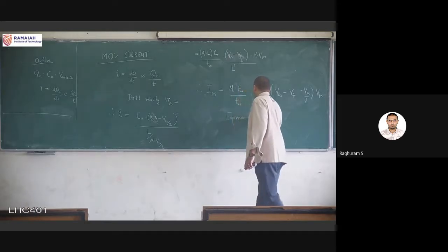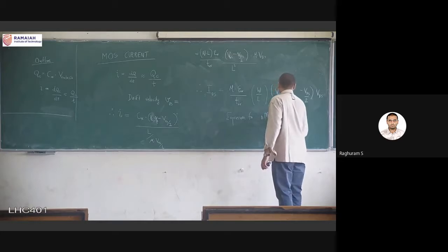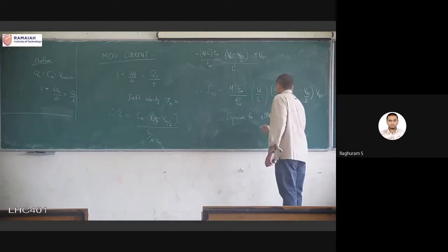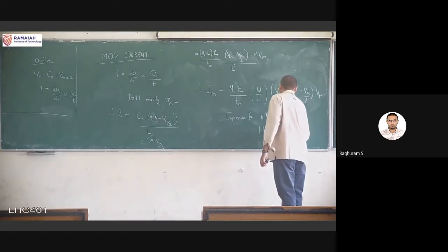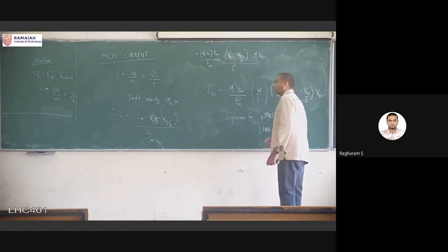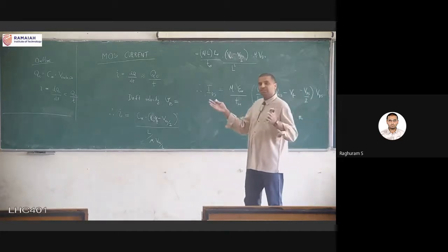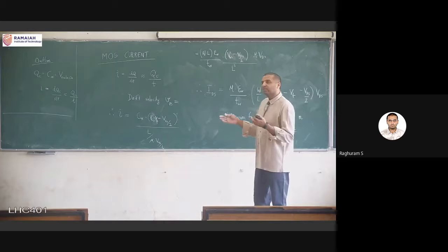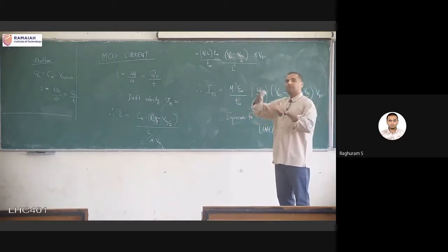This is the expression for NMOS current in linear mode. Why is this in linear mode? Because in all the derivations for the distance the electrons are traveling, we have assumed that they are traveling the L, that is the channel is existing from the source to the drain.